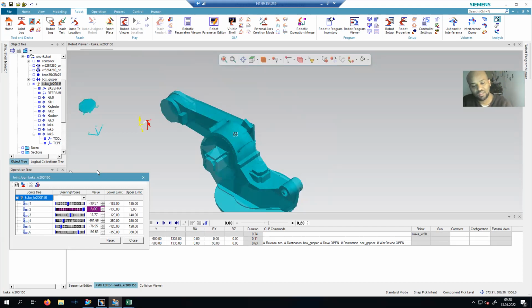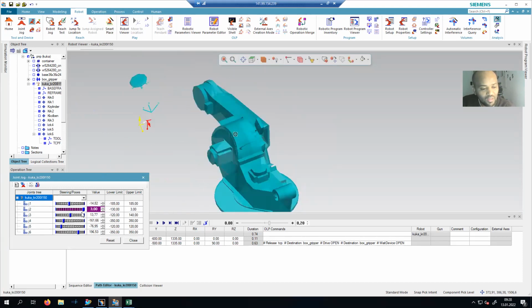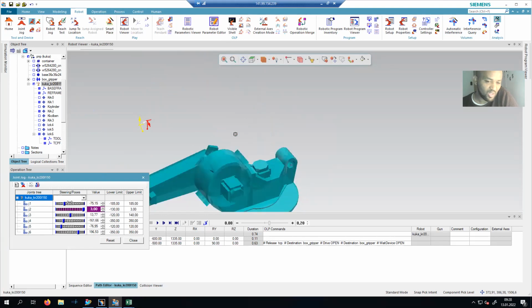This one is rotating this way, but this is rotating this way, which is opposite, 90 degrees to each other. So this is the offset angle, which we call the twist angle. Now we have the offset distance, the offset angle or twist angle, then the joint angle.